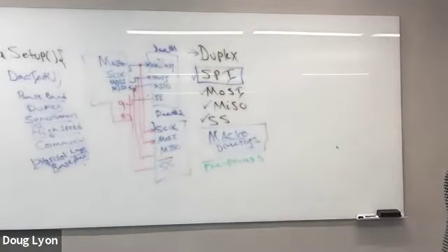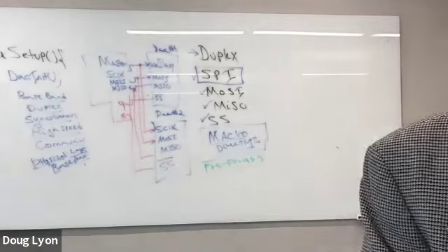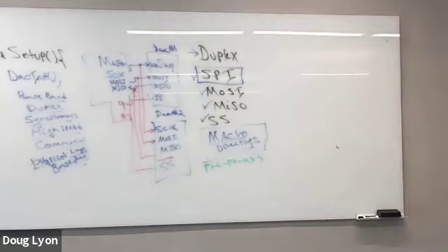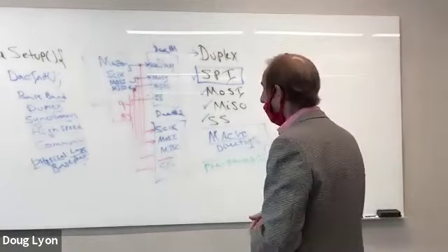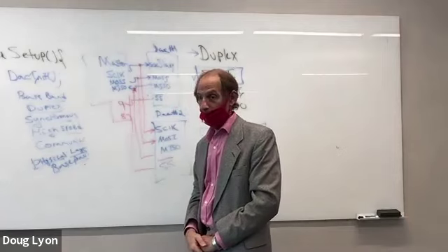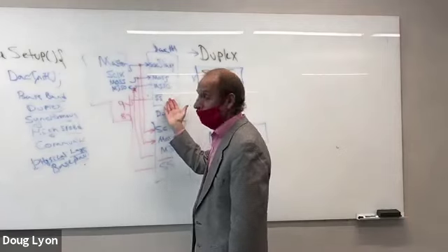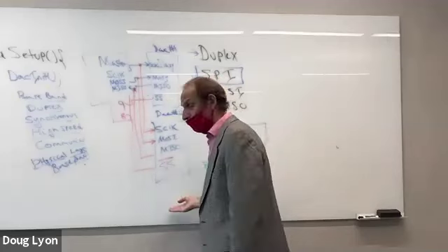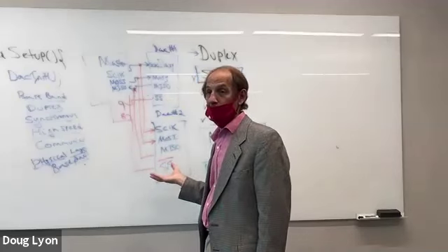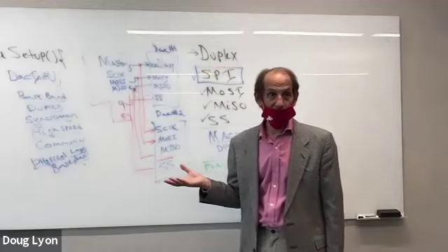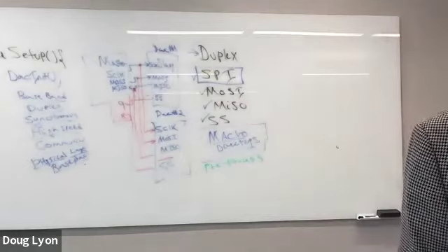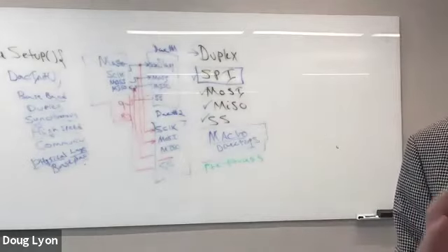And taking turns is the essence of enabling what I would call a simplex-only communication path. You can't have this turn into a party line where all of the devices talk at the same time. When there's just one device, sure, it's full duplex. But when there's multiple devices, even though they're the same exact device type, you've created a simplex system where things have to take turns. And that's important to notice, right? So what has happened is the configuration enables simplex-only communication.